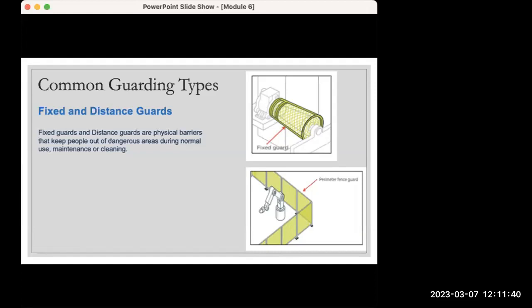You must also consider the height from the floor surface to the structure and the distance to the danger zone to determine what body part can enter from under. The distance from the floor surface to the structure should be less than 180 millimeters to prevent a whole body entry. Fixed guards where used should safely contain any broken parts and allow for any safe lubrication or other minor adjustments without the removal of the guard itself.